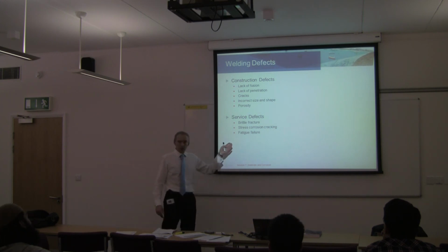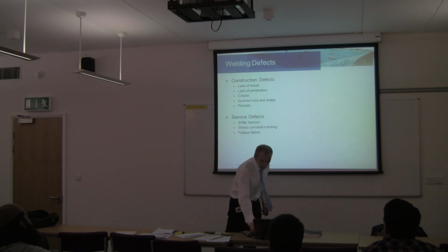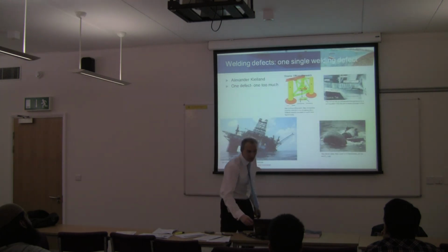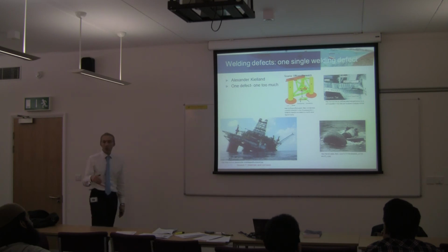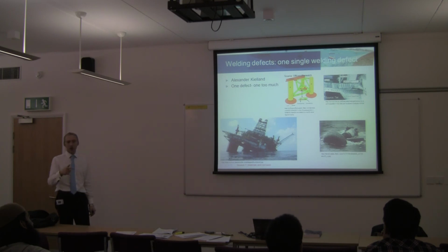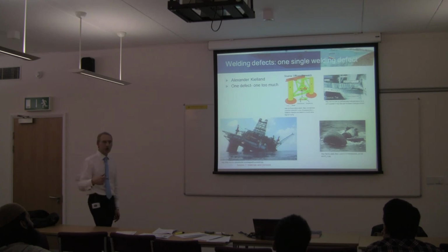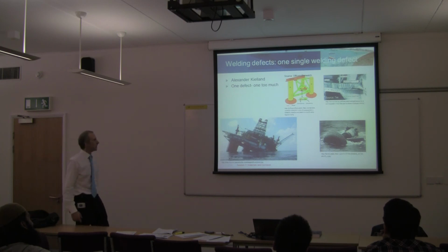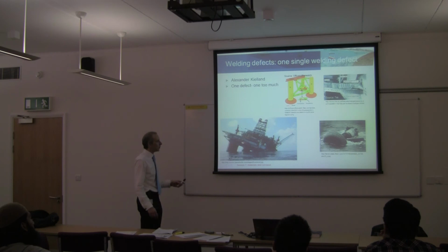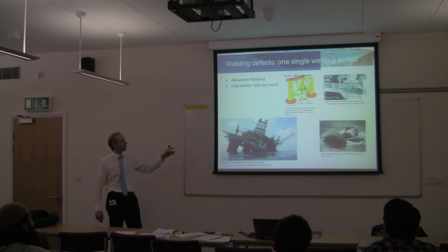The stress cracking can also be induced by hydrogen. It's another byproduct of welding. When you weld the pipeline together, you introduce hydrogen into the metal, and that can lead to hydrogen-induced stress cracking. Again, disasters. I said that there's been many before, and there's been some recently since that video you saw earlier.